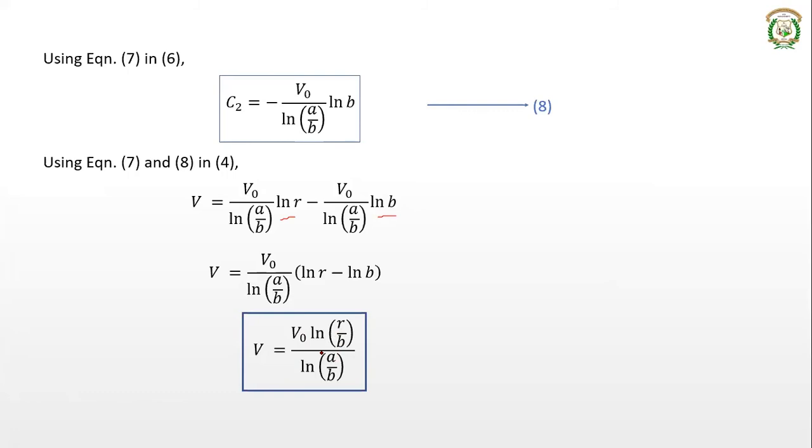Now, in our steps to find the capacitance, once you find V, we are supposed to get E, that is electric field intensity. What is electric field intensity? E is equal to minus del V. Now, this del V has r, phi, and z components. Since V is a function of R alone, we take only the R component, that is dou V by dou R into AR. The phi and z components are eliminated because they are 0.